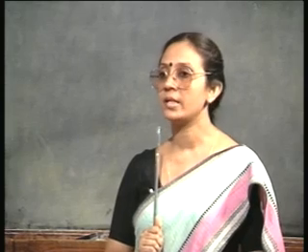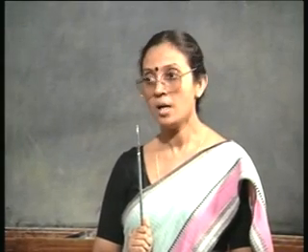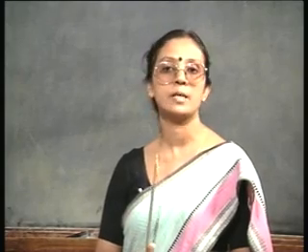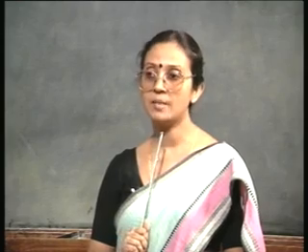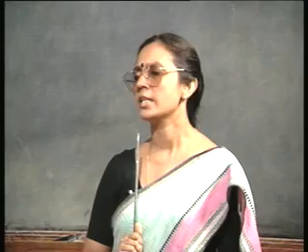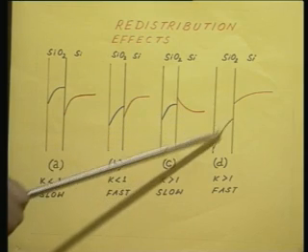Okay. I now come to the final variation of the theme, that is K is greater than 1 but it is a fast diffuser. I have already given the example of gallium. Gallium is an example of this. Gallium has a segregation coefficient greater than 1 and gallium is an extremely fast diffuser in the oxide. This figure, however, is a bit more confusing.